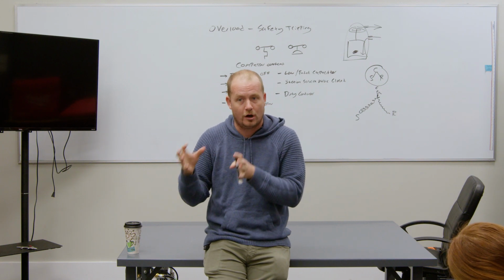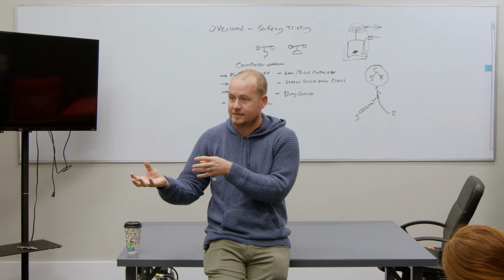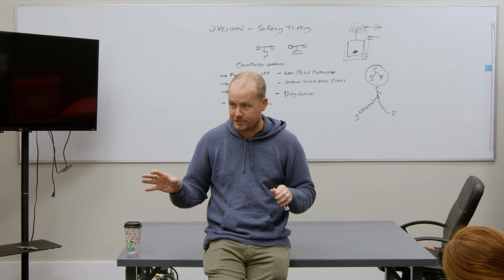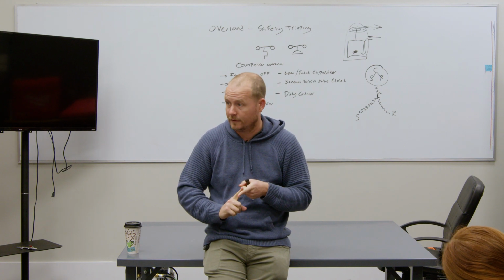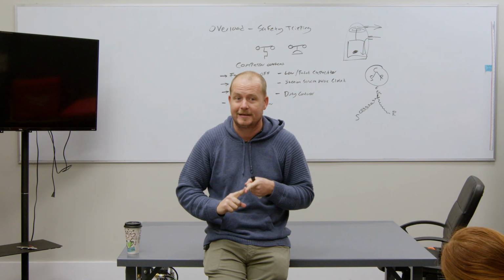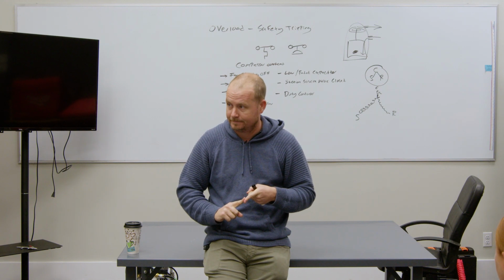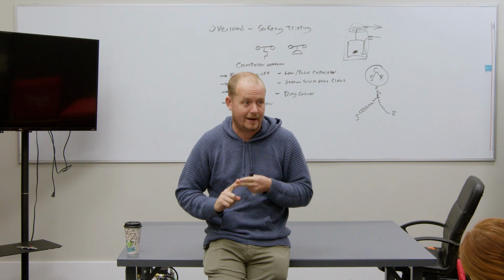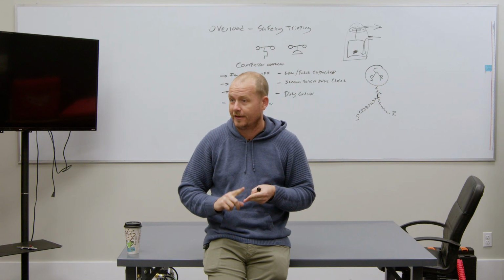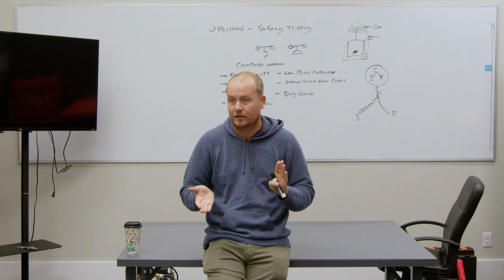But figure out what caused that safety to fail before you just order the safety. Do you all understand what I'm saying? So if it's a high limit on a furnace, for example, figure out why it was tripping on high limit, because the high limit doesn't just fail. If it's a high pressure switch, figure out why the high pressure switch was tripping, why it failed open, because they don't just fail. They fail because they've been smacking open and closed so much.